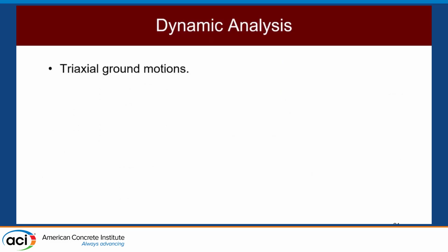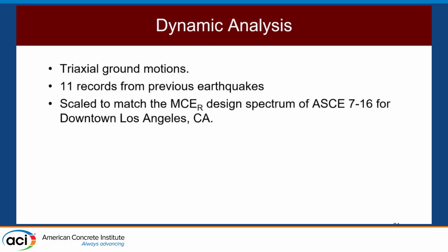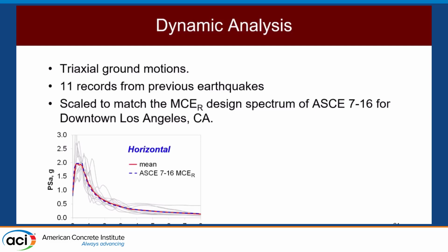So the dynamic analysis used triaxial ground motions from 11 previously recorded earthquakes. We have an X and a Y on the ground plane, and then we have a vertical direction as well, scaled to match the maximum considered earthquake.